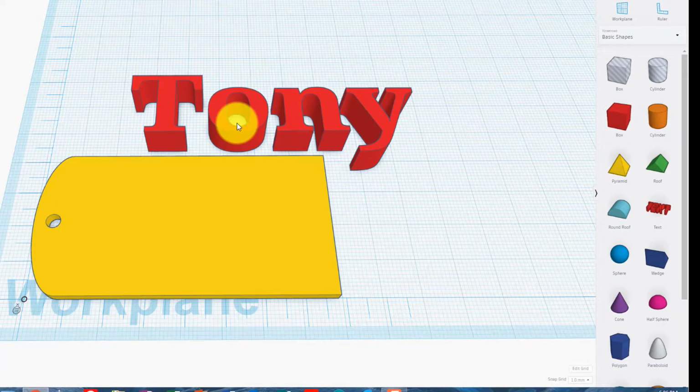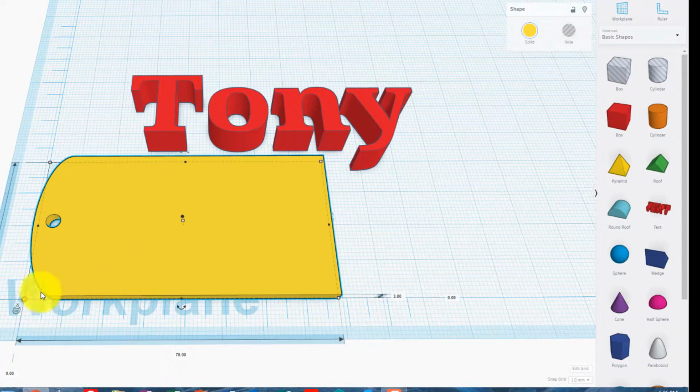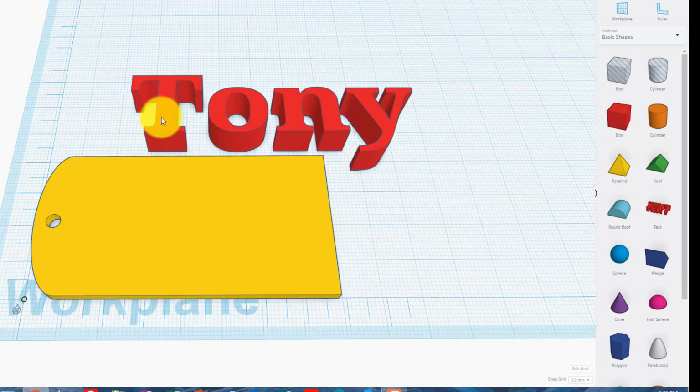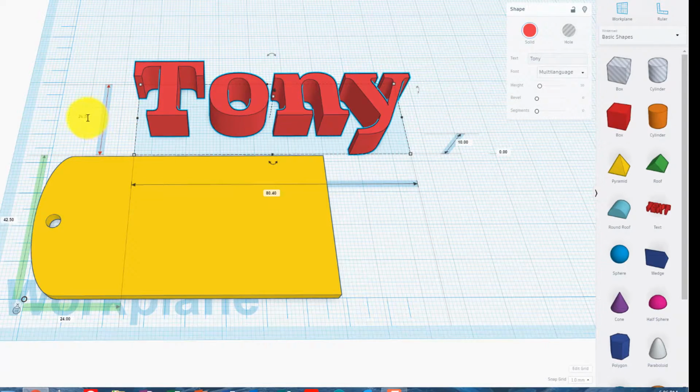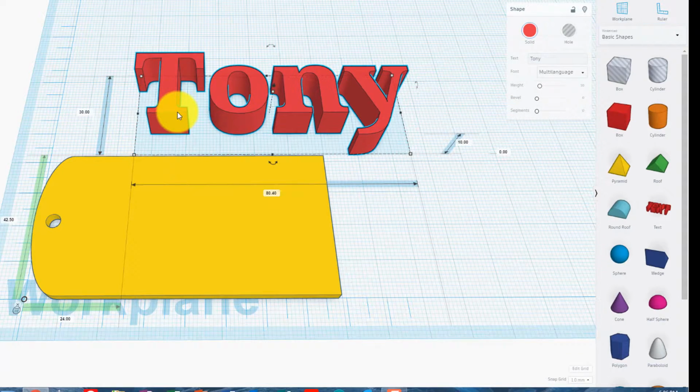So it said in the task sheet that your name should be centered in the badge, and it should have a 5 millimeter border. Well, let's work back from there. So we know in the Y plane we've got 40 millimeters. So if we have a 5 millimeter top and bottom border, that's going to be 40 minus 5, which will be 30. Great, so we know this in the Y plane can be 30. The Tony, or whatever your name is, can be 30. It's currently 26, so I'm going to make it 30.